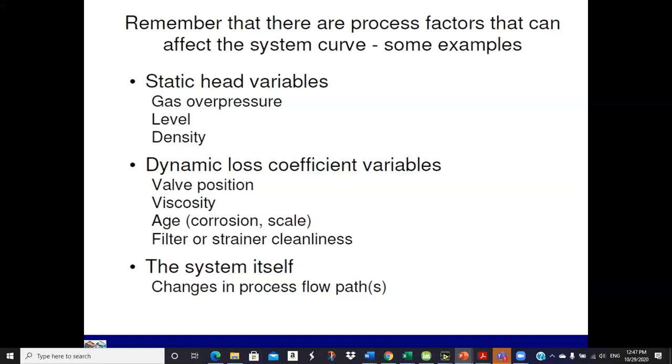Viscosity: again, you have temperature changes, so you can have viscosity changes, and that will affect the dynamic losses in operation of the pump. If it's small changes, it isn't that much, but if you get a significant change, then that has to be considered.